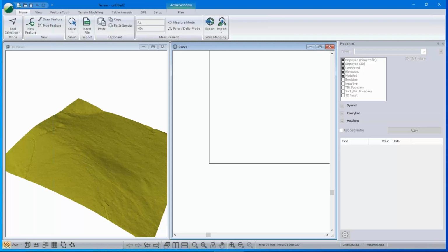LiDAR points are usually around 1 decimeter accuracy, 3 or 4 or 5 inches, and the total station, of course, is millimeter accuracy. Well, the trick is to cut out a hole in the LiDAR and insert your survey data. It's actually not so different from that contour question in the sense that you need to remove a piece of the LiDAR data and then insert the survey data in the hole and then rebuild your model.